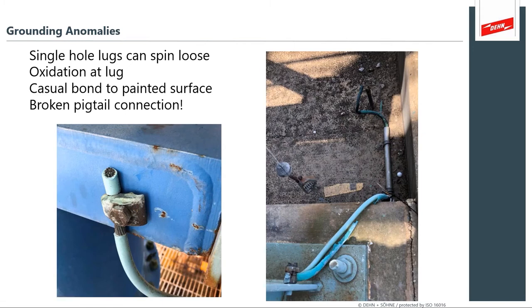And so you might be experiencing instrumentation problems and troubleshooting your instruments, and it's not the instrument, it's the earthing and bonding. That's why it's really important to pay attention to these maintenance issues that you can visually inspect. These are the things that you have control of.